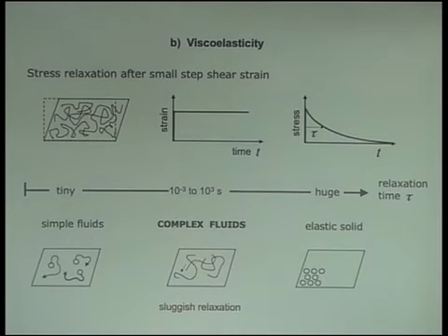On the other hand, in these complex fluids, what we have is a very sluggish process, again, of Brownian relaxation, but now, for example, these long chain-like polymer molecules have to slowly disentangle themselves from each other, and the stress decays then slowly on a timescale that's commensurate with human observation, which typically makes these materials actually rather nice to do experiments on in the sense that the timescales are those of human beings.